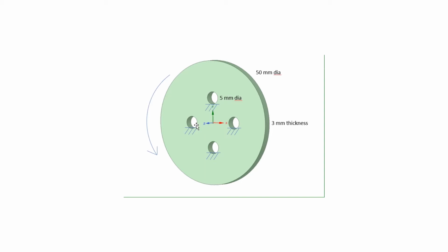To perform a topology optimization in the disc, we first need to perform a typical static analysis. We then load in a topology optimization analysis system to perform the optimization. We want to have a relatively fine mesh to obtain a more accurate optimization. We will begin by building the model in SpaceClaim. We will then do a static analysis and then the topology optimization.